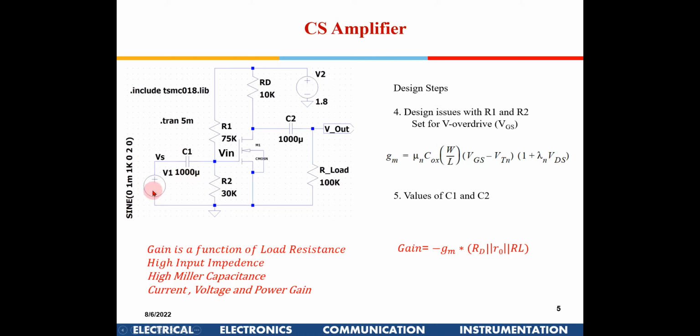But if it is being driven by an antenna which has 50 ohms, at RF frequencies the low resistance of the antenna and the high resistance here will result in impedance mismatch, and standing waves will be formed. That is not desirable. So high input impedance is good as long as this is being driven by another CMOS amplifier, but for certain applications this is not a good feature.